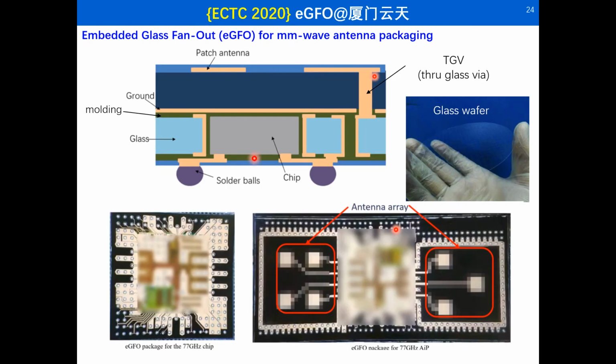In this page, we are going to introduce embedded glass fan-out, EGFO, presented by Shenghua Yuntian, a Chinese company on wafer-level packaging. Glass is used as the substrate wafer, and it is a simple technology without temporary bonding and debonding process in the fan-out process. Perhaps it will have lower dielectric loss for high-frequency operation. The chips are embedded in a glass wafer frame.